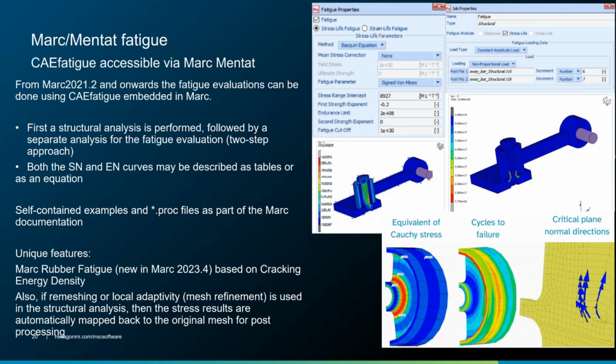So to estimate the fatigue life of an elastomer component, and this is using a critical plane and linear elastic, once again, crack energy density and a Paris law-like tool to determine that. And it's extremely well integrated and very specific, obviously, for elastomers. This is something that we delivered only recently, but it's coming through very nicely.